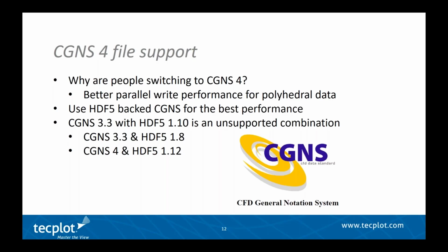We also found that there is at least one combination of the CGNS library and the HDF library that is no longer supported in CGNS 4. And we brought this up with the CGNS community. They're aware of this issue and have a bug that they're tracking against it. But for now, if you are using CGNS with HDF5, prefer using CGNS 3.3 with HDF5 1.8 or CGNS 4 with HDF5 1.12, and you'll get the best results.